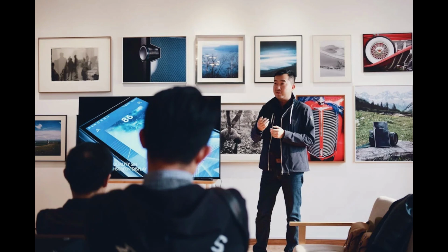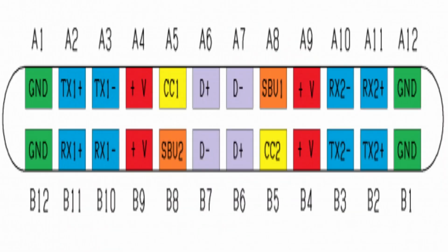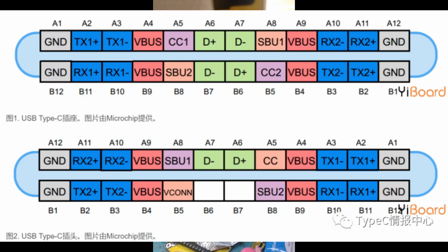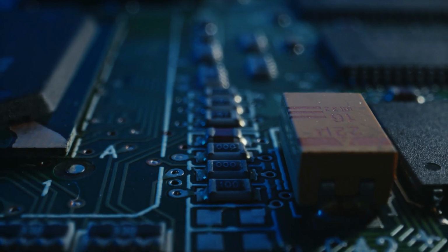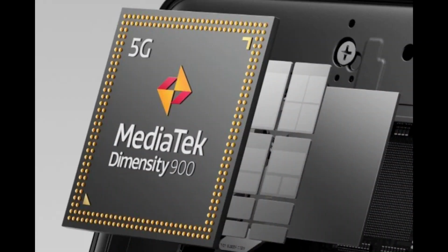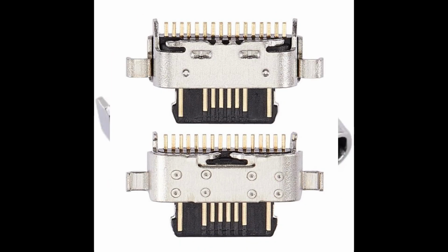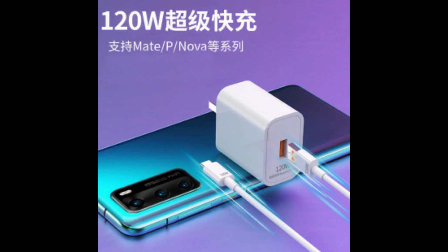The answer is, if the company uses a 24 pin with all pins working, just like in flagship phones or premium quality phones, and uses the same working pins in economical phones, then the company has to make a lot of changes. They will have to put in a high brand CPU for this, because in a 16 or 18 pin or 24 pin, USB 2.0 works for the data lines, but in a 24 pin you will see USB 3.1 or 3.2 data lines working.